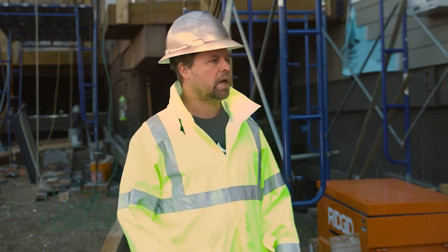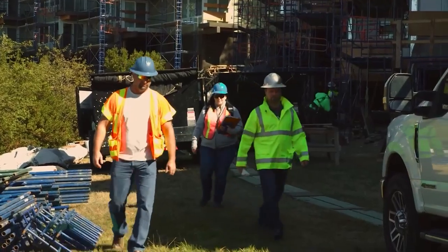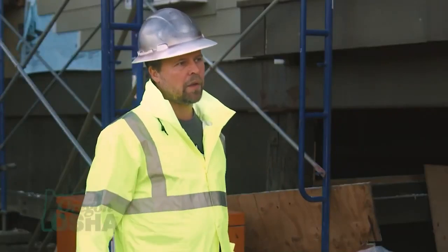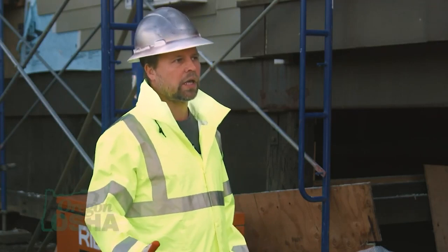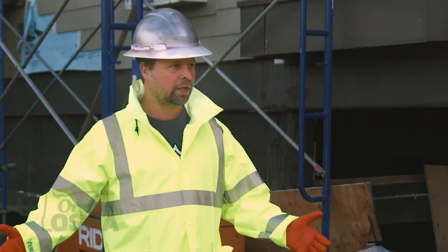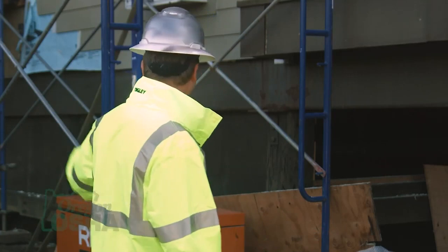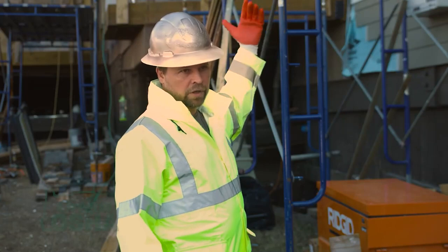So our supervisors will inspect it with the guys, and we'll have different crews go to each other's scaffolding as well to look for different things, make sure everything's proper, and point it out. Because as you become accustomed to your daily routine, sometimes you don't notice, like, hey, there are too many screws here, and there's some lumber here that you can easily knock down and it'll fly over. Same thing for the guys walking around. They have to be aware. We don't want it, but what if something falls?